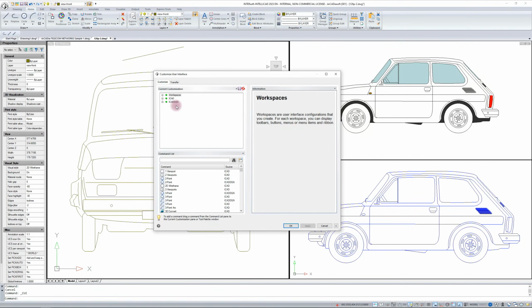Please do not expect that under the letter R there will be, for example, a rectangle, because someone would say that I would like redraw, and I would like a regen, and I would like something else. The aliases are defined under the English command so that the lines are okay. However, the other aliases are already likely to mean something different than what you might expect. Therefore, it would be a good idea, as far as aliases are concerned, to simply look for yourselves to see what is under a given letter. If something doesn't suit, we can change it, of course.